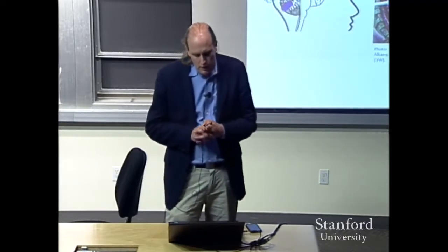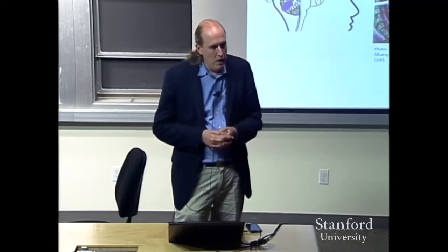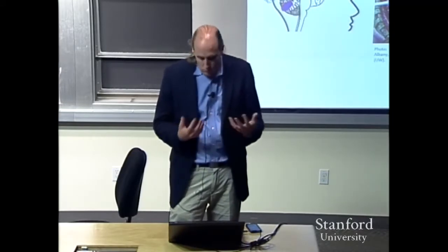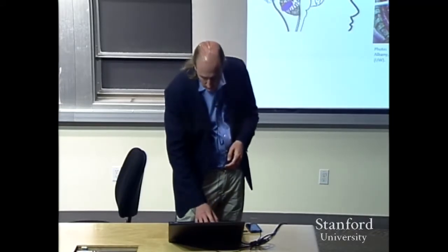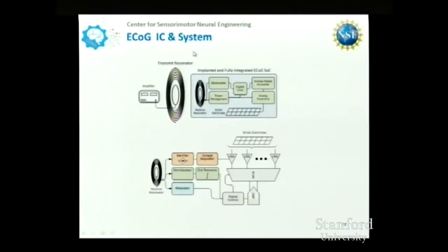But the thought is that if you could completely implant an ECOG system, then potentially you could put these in and leave them there basically permanently, which could be used for these therapeutic purposes, but also potentially for brain control interfaces and things like that. So in this application, we're very size constrained because the goal is to put the whole thing inside the skull. So we have to do a chip for this. Working with my colleague Brian Otis, we're designing an ECOG chip that can be wirelessly powered using our HF wireless power system.